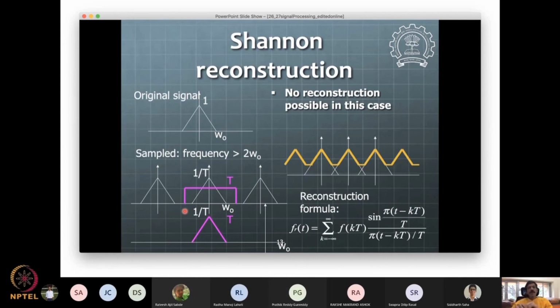It's the same idea: you have an input represented in the frequency domain, a transfer function represented in the frequency domain, and the output coming as a frequency domain representation. So the two are not different. The filter is not different from any kind of transfer function thinking in the Bode plot domain. Okay, so that is an important concept.